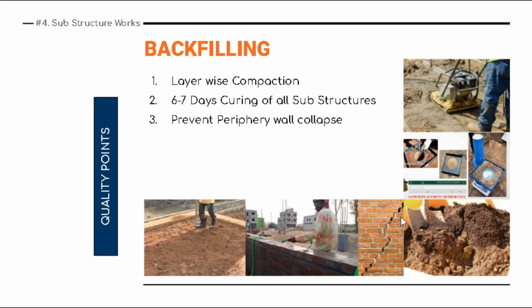And again, sometimes you're in a hurry, while you are doing a parallel activity, meaning you are again raising the brickwork of the periphery brick wall and simultaneously you are putting in a lot of sand. Maybe that brick wall will not be strong enough to hold the sand, and it may eventually crack. Okay, so be very careful about that.